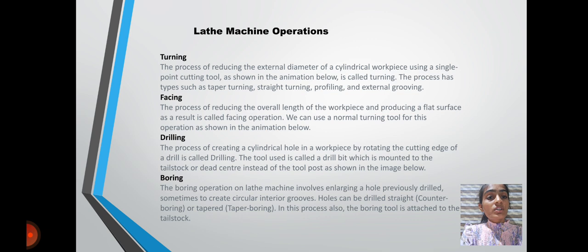Facing. The process of reducing the overall length of the workpiece and producing a flat surface as a result is called facing operation. We can use a normal turning tool for this operation as shown in the animation below.